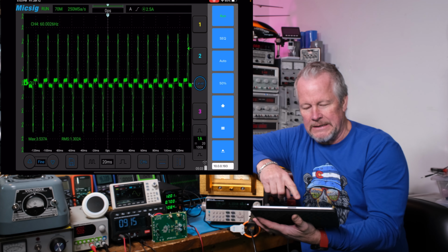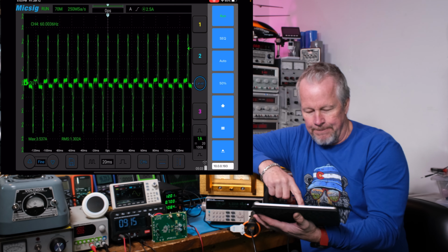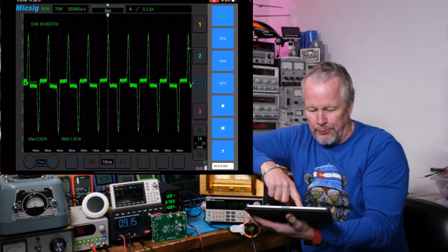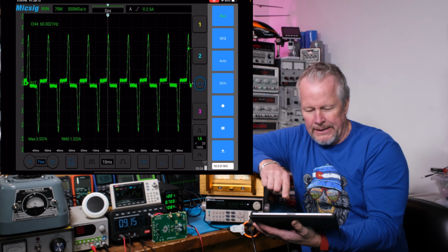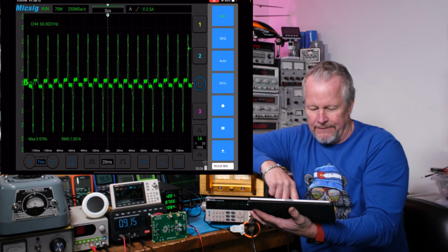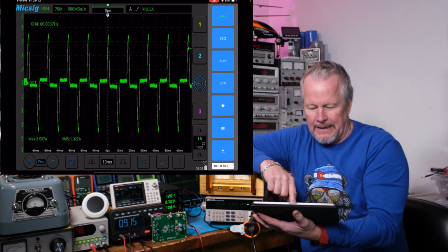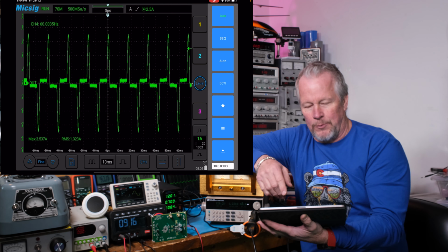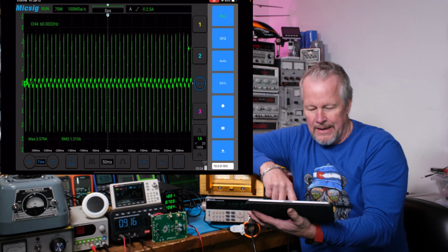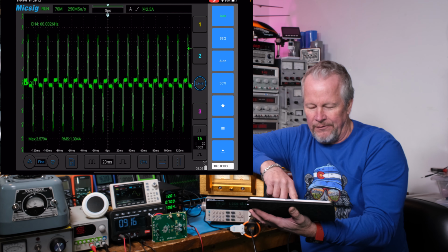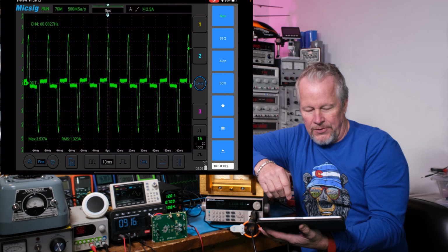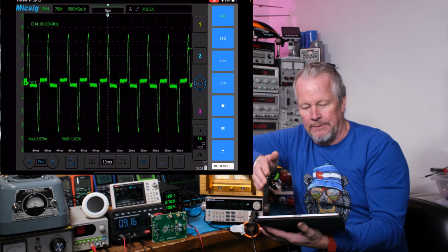We're zooming in a little closer. You can see it's off, and then a spike of current, then on. We zoom in a little bit more, we can see a little bit better. Now we look at the RMS current, it's like 1.3 amps, and the peak current is 3.5 amps. Let me get a few more cycles and see if the current gets, yeah, it's staying about the same. With more cycles the math works out better, so you can see the numbers change a little bit. But it's right around 1.3 amps, 3.5 amps peak. So peak currents are, not 3 times, but 2.5 times higher, something like that.